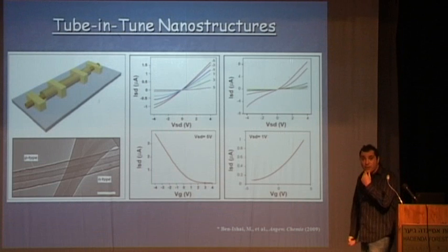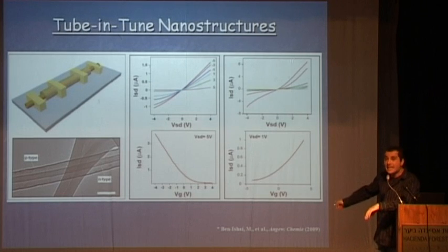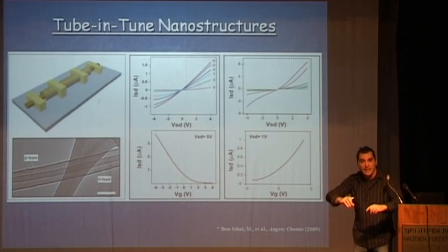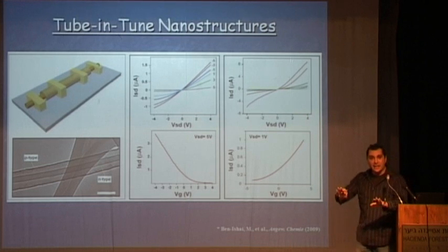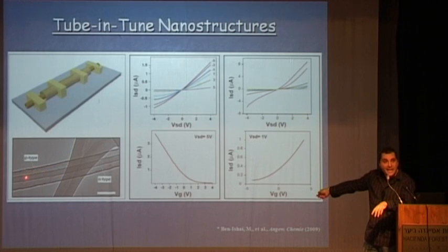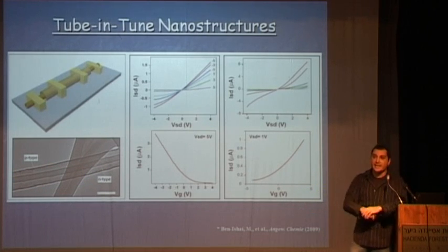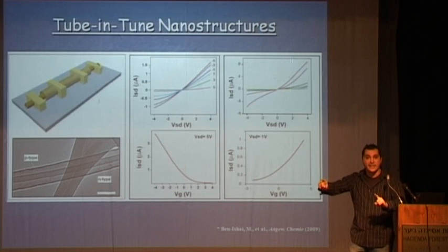Also, we can imagine building electrical devices of much higher complexity. We can take a single nanotube with 2 walls, and by a particular process, with the help of Alex in the e-beam lithography, we can make electrical contacts with each one of the walls of the same nanostructure. So let's imagine that we have a nanotube with an interior tube that is N-type doped, while the exterior nanotube is P-type doped. By using the same nanostructure, we can create electrical devices that have a dual electrical functionality.